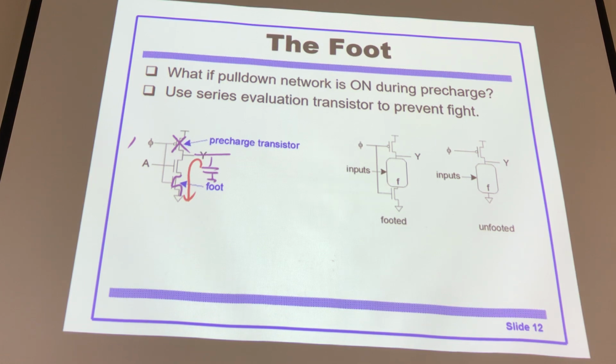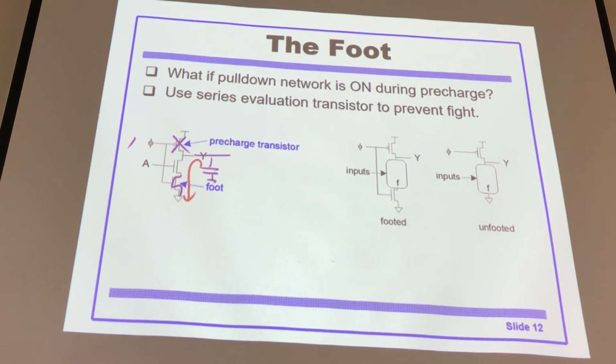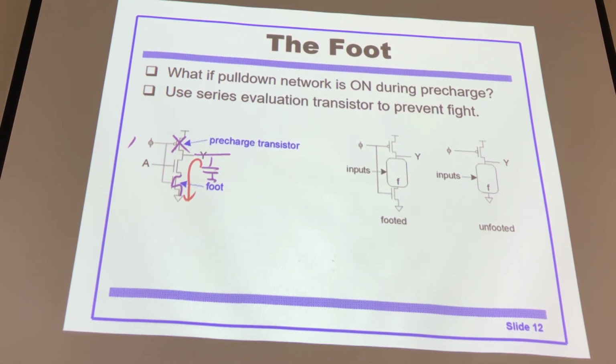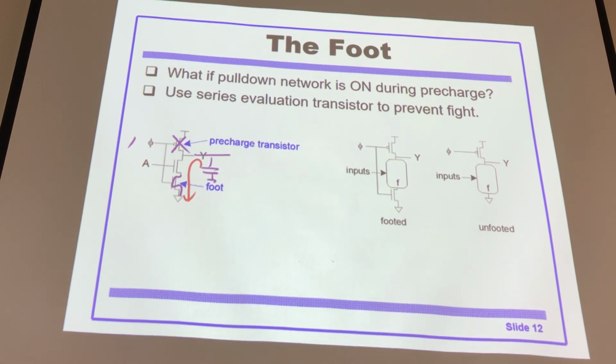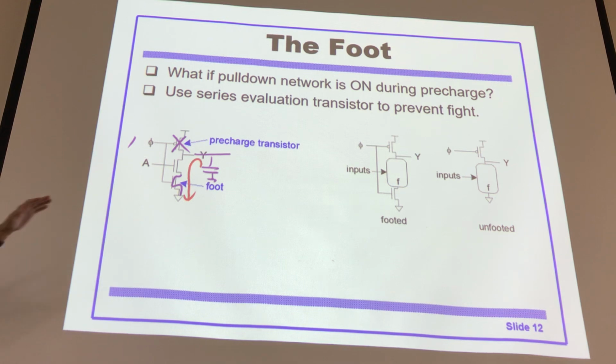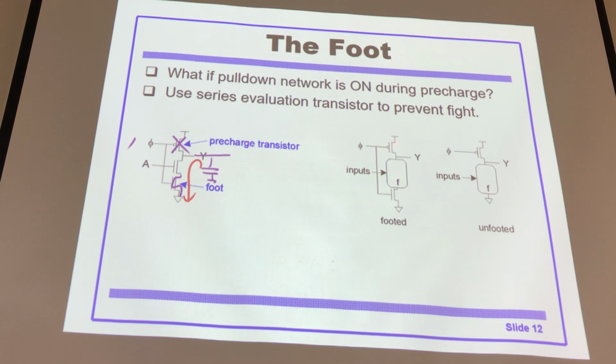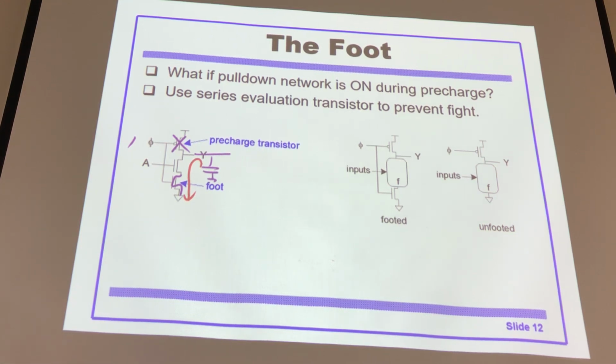They are smaller. Smaller, okay, good answer. Well, yes, for an inverter, no, it's not smaller. But yes, if your circuit has quite a few transistors connected, just like pseudo-NMOS, you only need one PMOS and one NMOS, and the same pull-down network. It could be smaller, yes. What else?